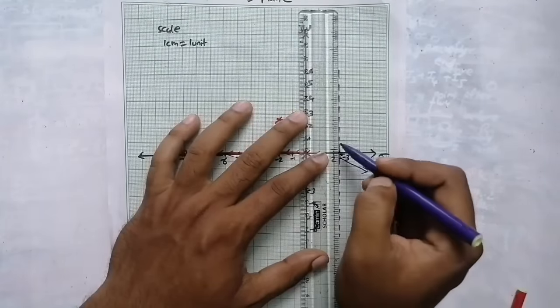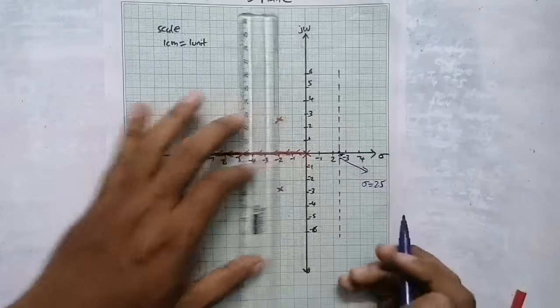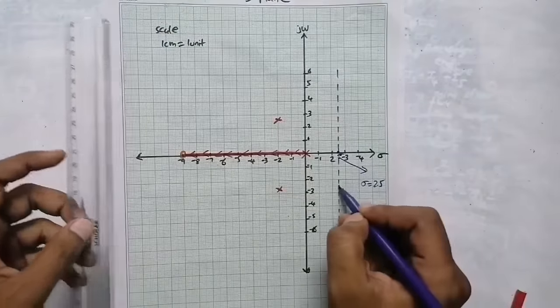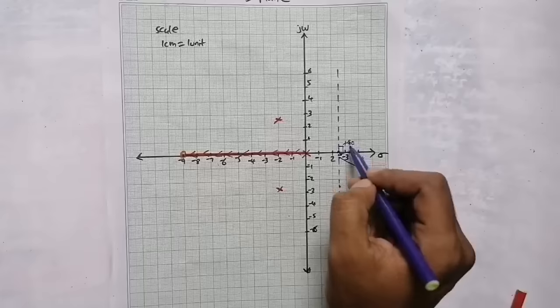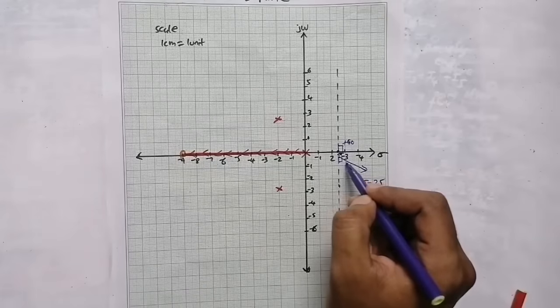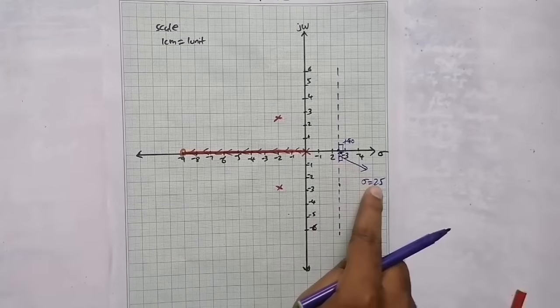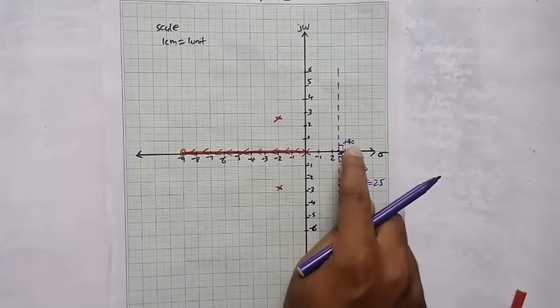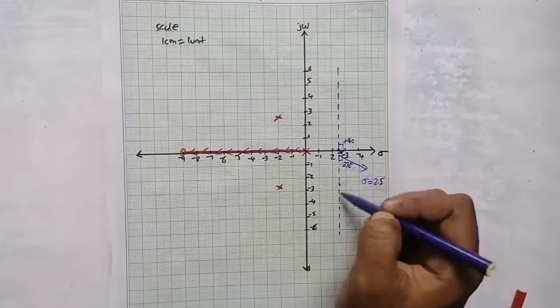And the same here, this is minus 270 and this is plus 270. So this is the angle of asymptotes. Now this is the asymptote and the angle of asymptote is plus or minus 90 degrees. So we have the centroid at 2.5 and angles of asymptotes plus or minus 90 and 270 degrees. Then this is the asymptotic line.